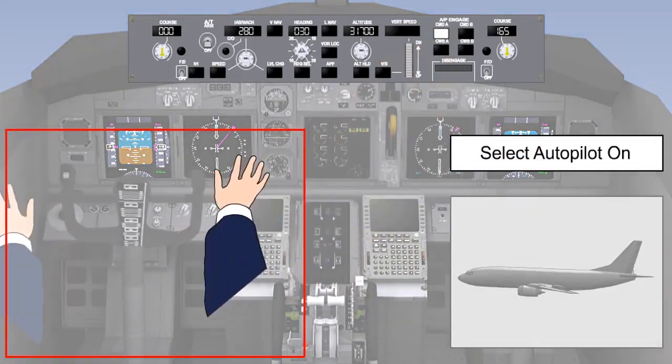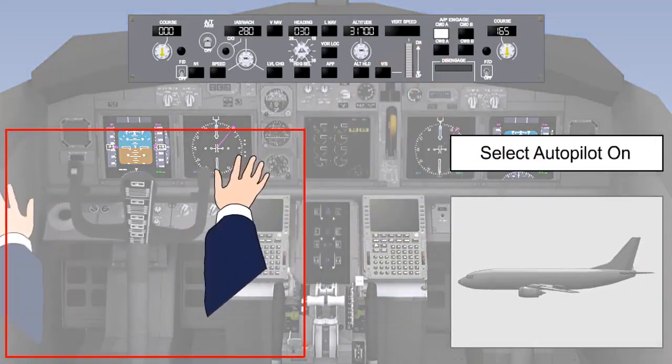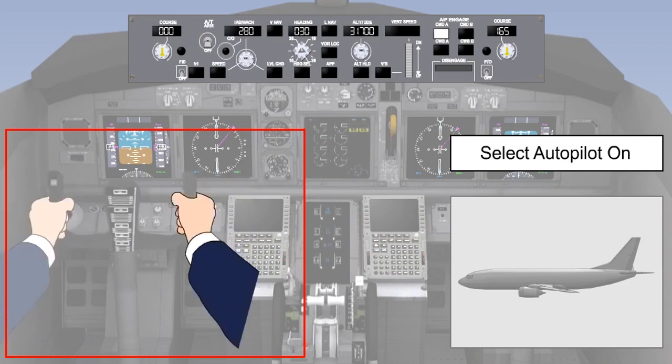When the autopilot is engaged, it has to be capable of continually trimming the aircraft in pitch to account for variations of the centre of gravity, configuration and speed. If this did not happen out of trim, forces would be felt on the servo motor, and at the point of autopilot disengagement, a pitch input would occur, causing the control column to be snatched or jerked. To allow for this, an automatic trim or auto trim system is fitted to continually remove any out-of-trim forces in pitch when the autopilot is engaged.